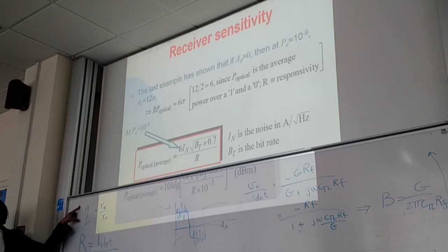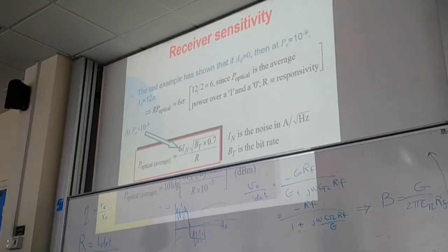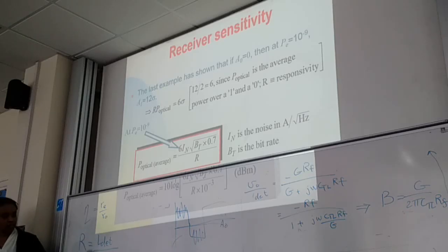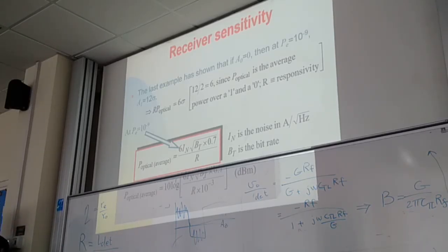The quantum efficiency is usually used to describe a detector, a device. And if you go back to the problems we have solved 2 lectures ago, you will see that when we talk about a detector, we say it has quantum efficiency of so and so. But when we talk about the whole system, the receiver, we will talk in terms of responsivity, because responsivity gives us values that we understand at the level of the system, at the level of the circuit.